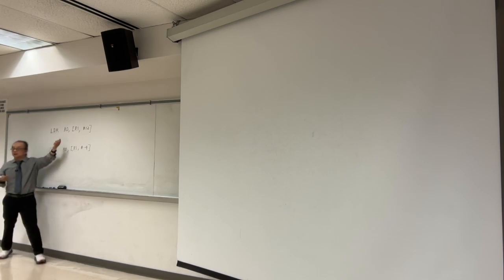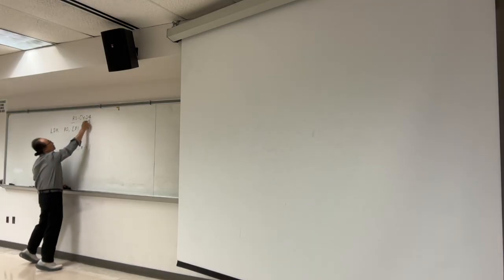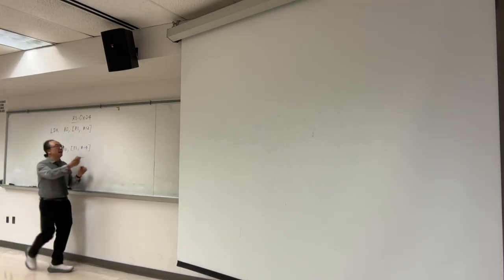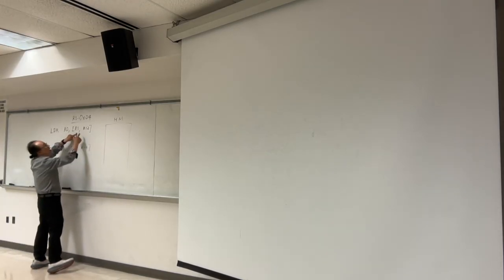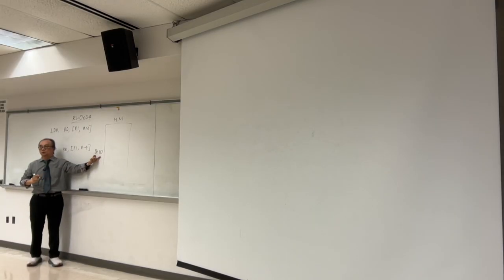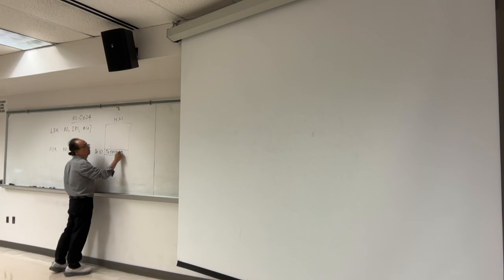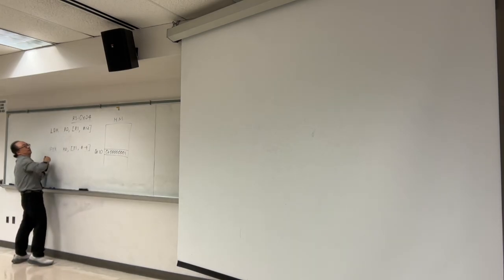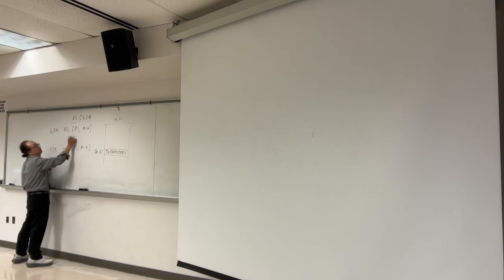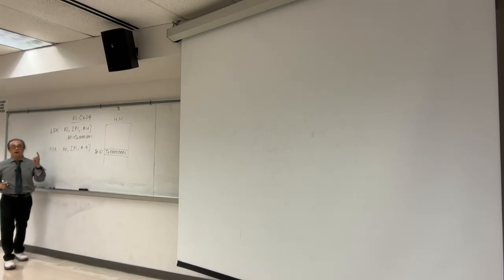LDR, we want to get into main memory, take that information into register. So let's say, as an example, we have R1 as 0x04. Now we need to go read the main memory, and memory address what? 4 plus 12, which is 16. It is hexadecimal, it's a 16. And read the contents, 0x12345678, store into R0. After this, we're going to have R0 equals 0x12345678. Make sense?